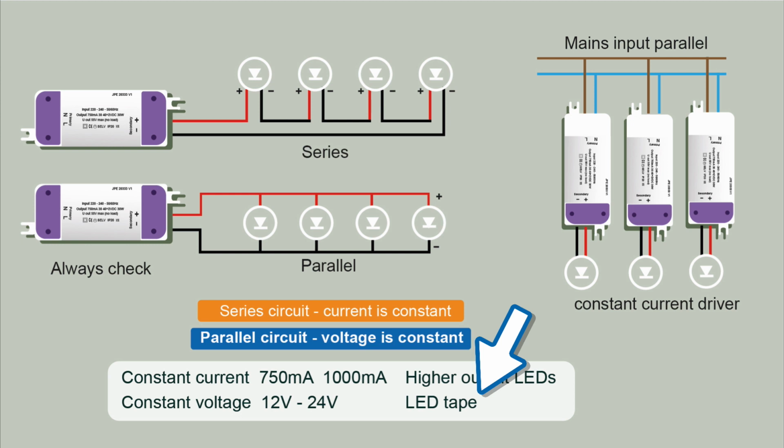When you're buying panels, you can specify the type of driver that you want. You often have to ask for a dimmable driver. They generally come with a non-dimmable driver. Dimming is often not a common feature, so you have to specify what you want to be able to do. Sometimes it depends on how it's wired as well, what driver you need.